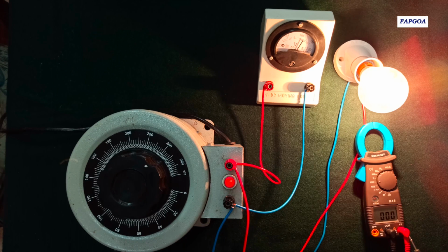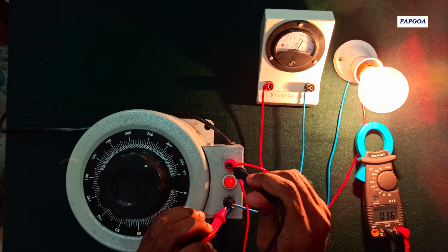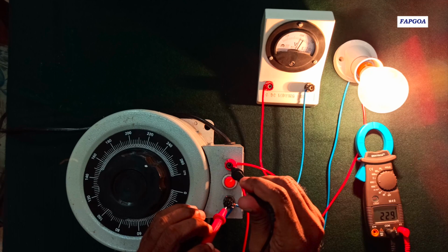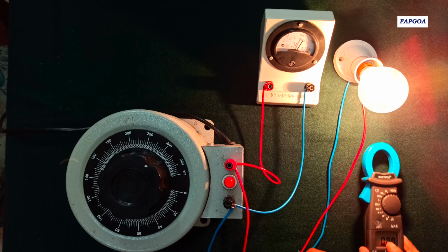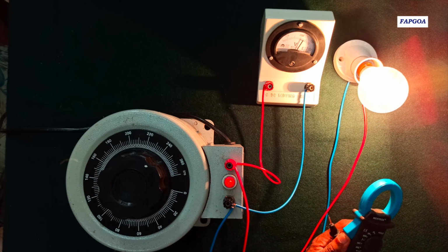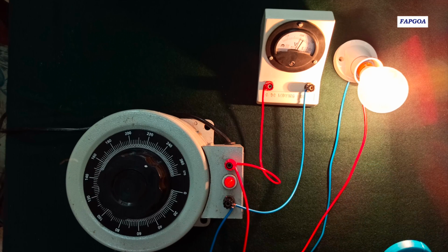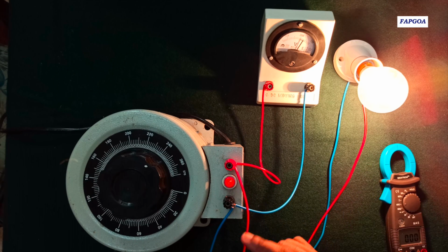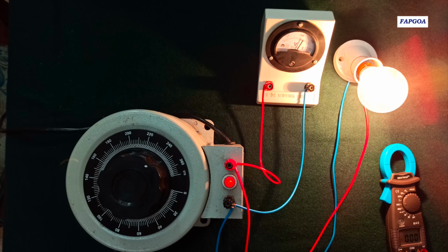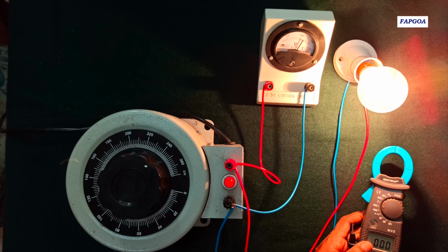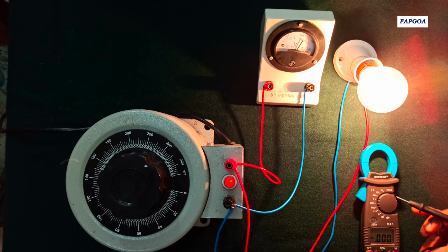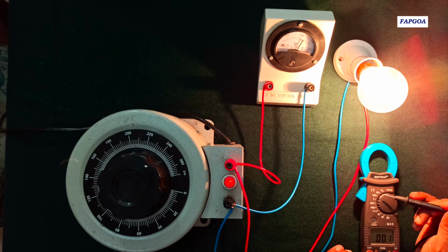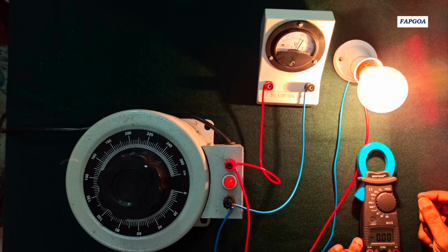You do not keep it connected, you use it across the terminals where you want to measure the voltage and then disconnect. As I have said earlier, this instrument basically measures electric current. Now, here we have current flowing through these wires. If you want to measure the current, you have to change the knob to 2 amperes. You can see here 2A, which stands for 2 amperes. If the current capacity is more, you turn the knob to 20 amperes.